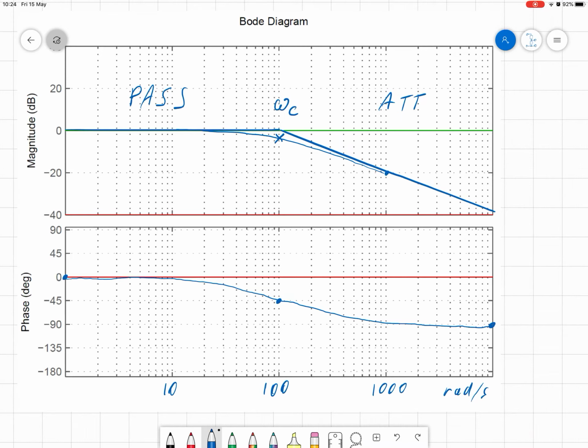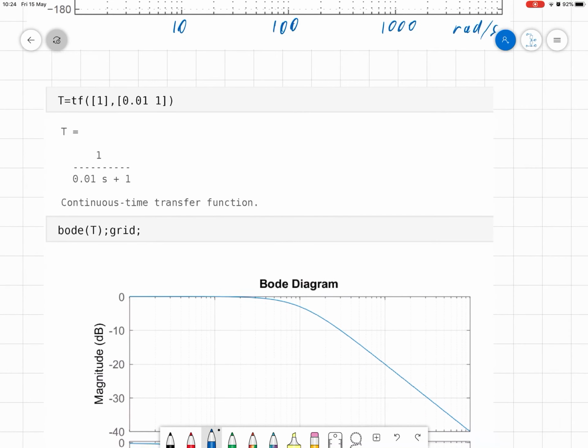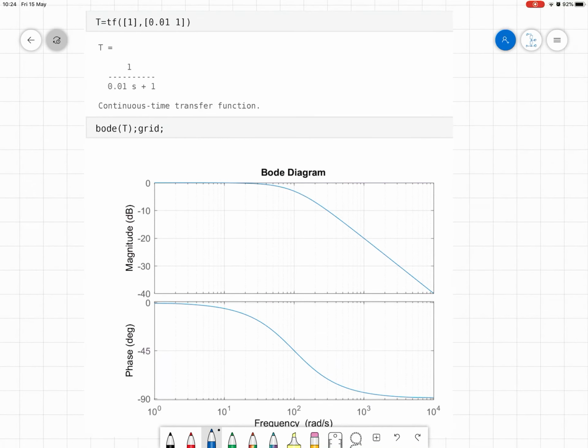Of course, you might say, seems an awful lot of work. We could just ask a computer to do it. And you're right, we can. So I have prepared this, and you can put this transfer function into MATLAB. You use the function tf. You specify your polynomials as vectors. You can see here it states our transfer function. The one difference is that it uses s instead of jω, which is just a question of notation.